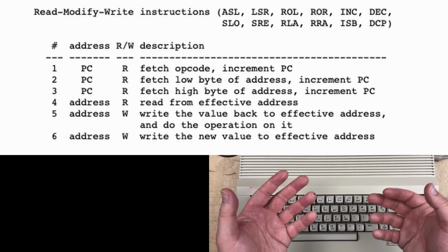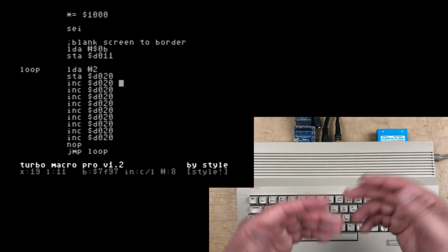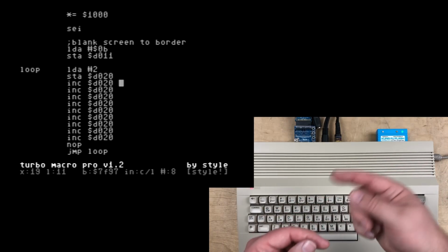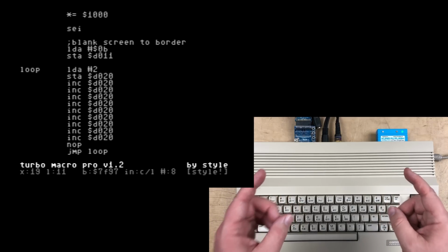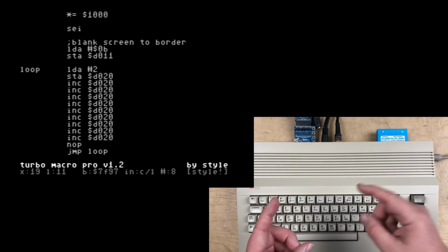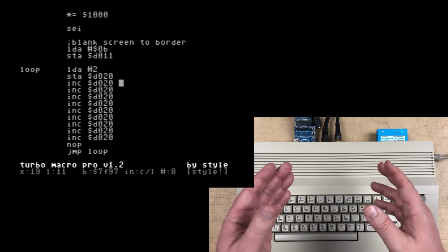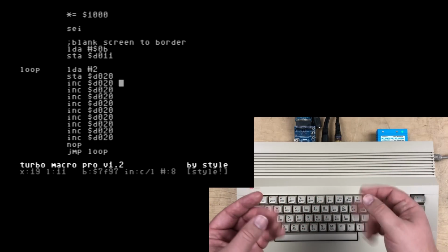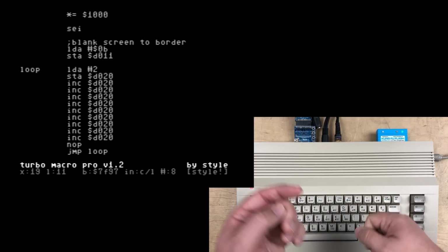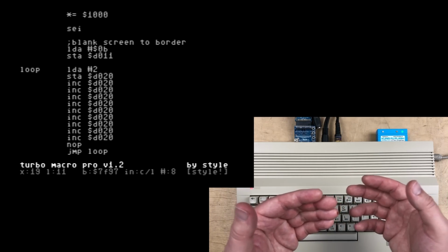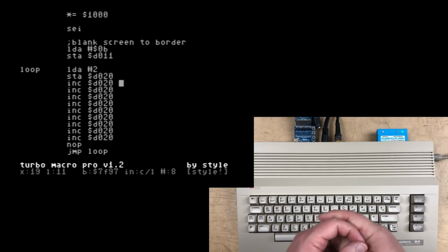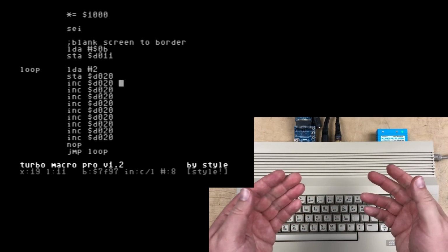You can visualize it. If you're just writing to a RAM value, you don't really care if the old value is written in briefly and then a new value. But when you're writing into these I/O registers, with video, it probably doesn't ever matter except for these visual artifacts. But you can understand how writing the old and then the new value to some kind of input-output chip might have bad effects. At least we should be aware of this effect.